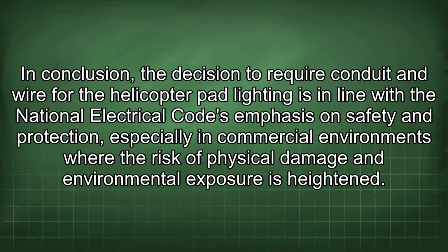In conclusion, the decision to require conduit and wire for the helicopter pad lighting is in line with the National Electrical Code's emphasis on safety and protection, especially in commercial environments where the risk of physical damage and environmental exposure is heightened.